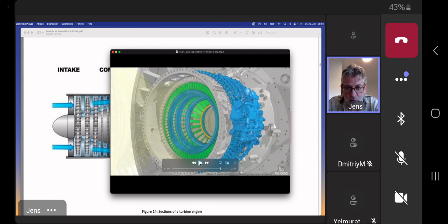We have to control the airflow through the compressor, otherwise we run the risk of a stall. So therefore, we have those VGVs, VIGVs, and an automatic adjustment. And also, another thing to avoid stall, those so-called bleed valves.